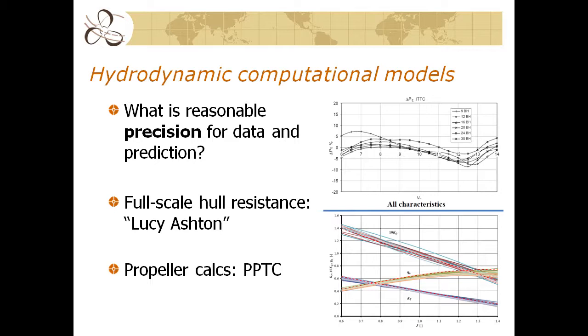But then what they did is they went and took models of different scale that very, very accurately reflected the geometry, including the sagging of the hull that was tested at full scale. And this is a plot of different model scale lengths. And if you look at the plus minus error, it's 5%. So the best of the analysis that we could do in model testing in order to achieve full-scale outcomes, depending on ship length and Froude numbers and the characteristics between wave making, drag, et cetera, really was about 5%. So anything less than that, you have to question whether that's realistically optimistic or not.